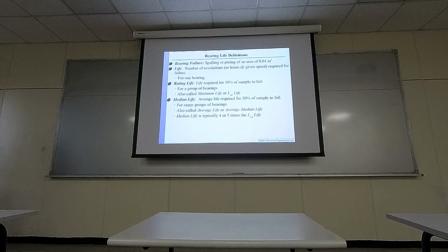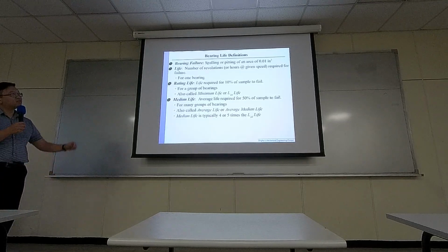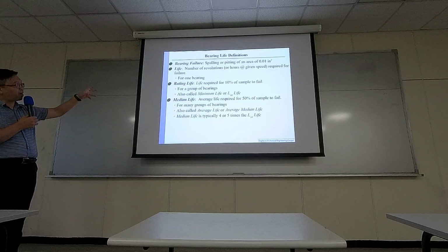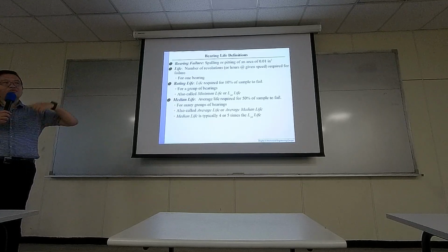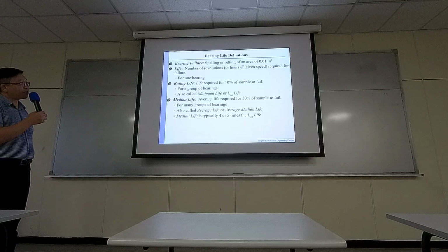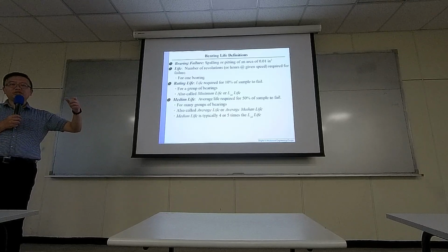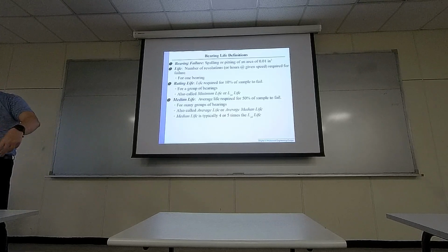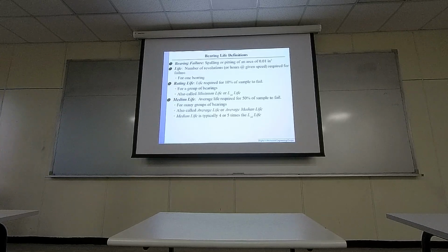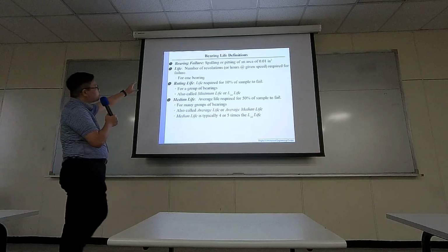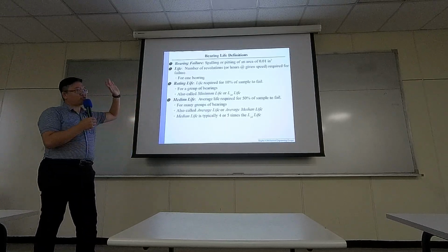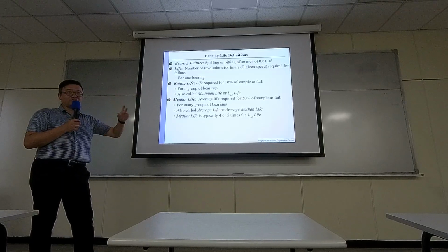So there is an important concept for bearings, which is the so-called life. And the life is defined by the number of revolutions, so how many cycles it's going to carry. But if the bearing is not carrying any load, you are just playing with the bearing like a toy, then it probably won't break, because it's not carrying much load. So usually when we talk about life, we also talk about how much load is being applied.